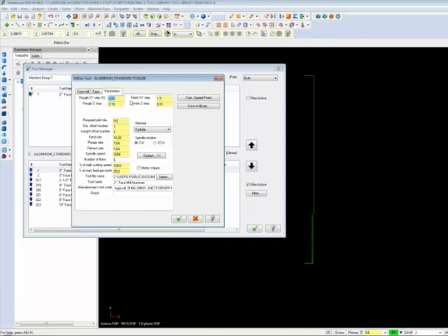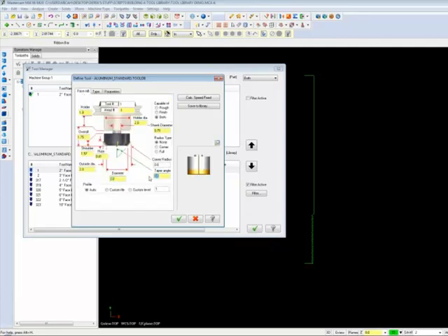So it's going to set your step over to the bottom diameter. If you had a standard 45-degree lead shell mill, say 2-inch diameter, with the bottom diameter at 1.6 and the outside at 2, it's calculating the step over to the bottom diameter. That's where it's figuring everything too.